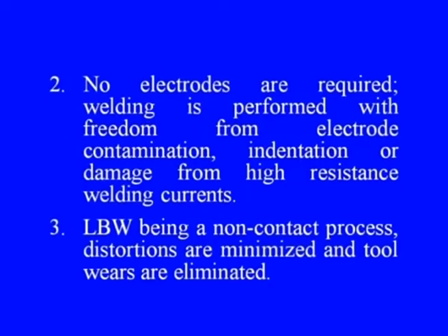In that case also, the beam can be concentrated to a very small diameter spot, and therefore, the heat affected zone nearby to this working zone will be much less. Number 2, no electrodes are required in this case.